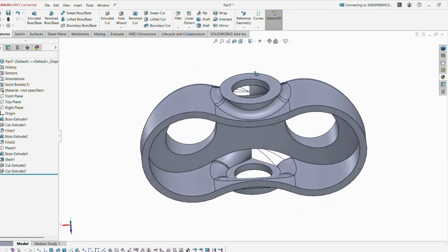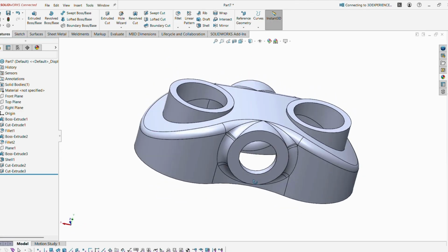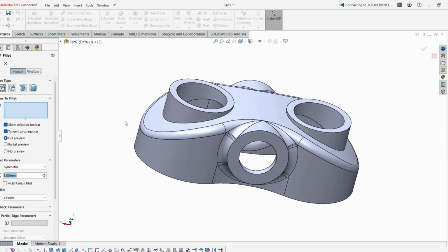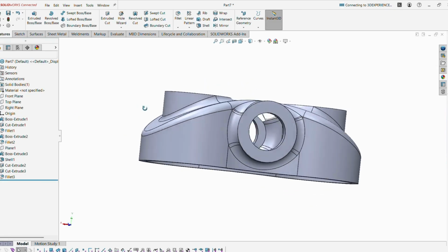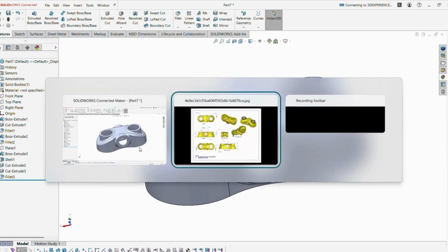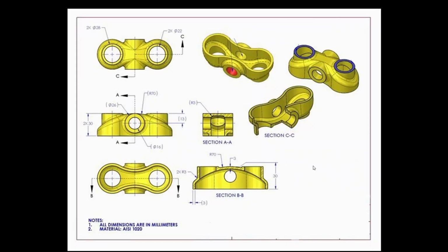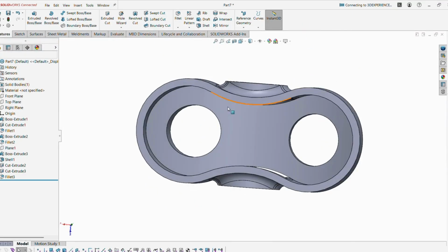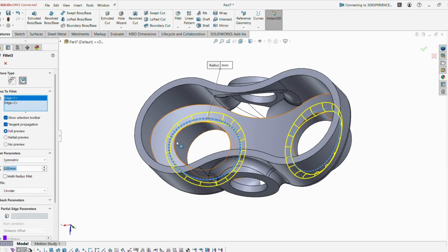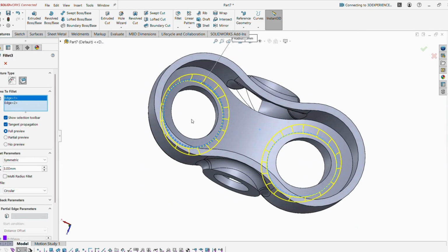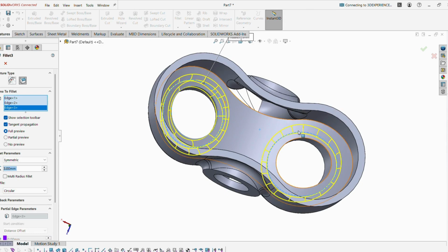If you want to use the fillet feature, you can also use it. Select all sharp edges and create tangential connections. Within 3 mm of radius, I am simply making that. Either we can create an innermost section also. If you want to create a shell feature at the right hand, go to the previous features and select another opposite circular edge at the right end.